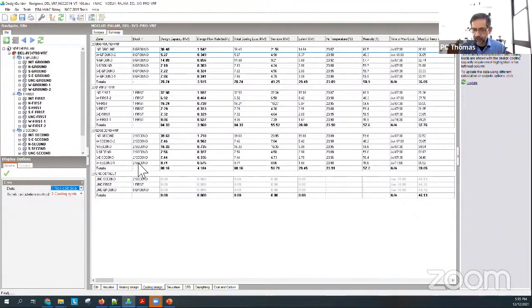So I've covered a lot of concepts, right? Hopefully you've caught most of that. Go and talk to a practicing air conditioning engineer. He will hopefully be able to understand and describe back to you what he wants, okay? Typically he wants these numbers in 3 different ways. He wants the chiller block load, or the block load for the condensing unit. Then he wants the individual zone loads, because then he can size the registers for each individual zone, okay?